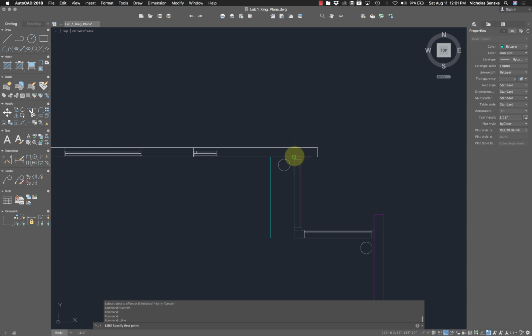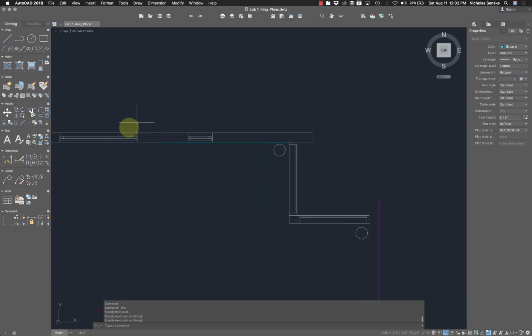And then I could go ahead and draw another line somewhere, and I could say offset. Maybe I want that one to be offset 1 foot 4 inches. Again, you'd have to take measurements, but it's pretty good. I got away from that column there, let's say.